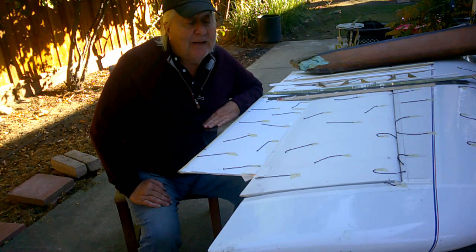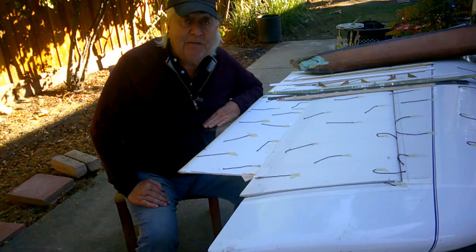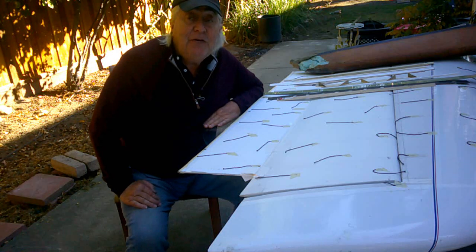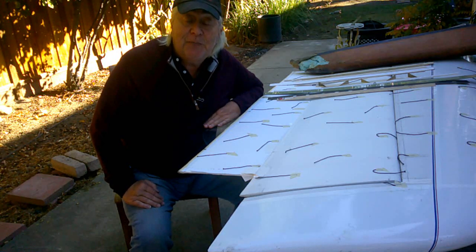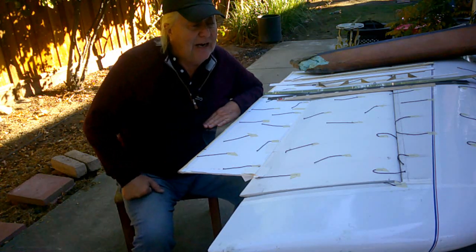Okay, and at that time I thought, oh, it'd be cool to be a foot-launched standard class sailplane. Let's make it 15 meters. Cool. And that's kind of where things were headed anyway. So I knew that a 15-meter span should be pretty easy to get in the range of 30 to 1 L over D, even with standard NACA airfoils.